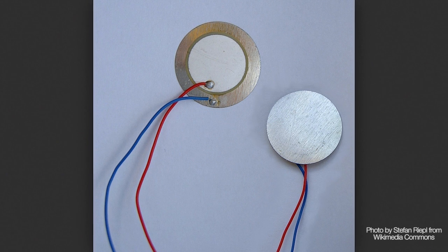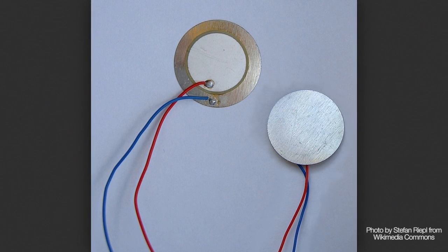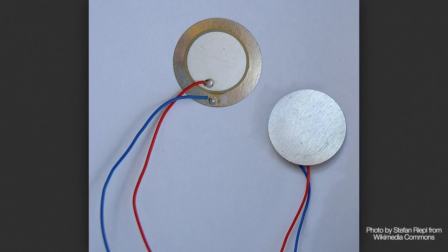There are a few other microphone types, like ribbon and piezo. Piezo microphones are pressure sensitive and are sometimes called a contact microphone. Piezos are almost completely insensitive to air vibrations, so they are not appropriate for voice. A ribbon microphone works a little bit differently. An extremely thin sheet of metal or nanofilm of electrically conductive ribbon is suspended within the field of a permanent magnet. When vibrations hit the ribbon, it creates voltage by electromagnetic induction.